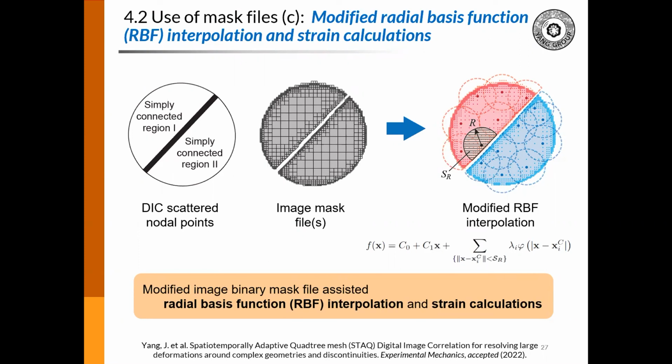The second one is that we get the DIC results, but eventually we need to use these results for materials characterization. You have lots of data points there, but how to do the material characterization more efficiently and faster? I think this needs help from machine learning methods. And because with DIC and DVC we can have data for the heterogeneous deformation field, we can generate quite a fruitful data set with far fewer experimental tests. So there's a bridge there that can combine DIC with machine learning characterization.